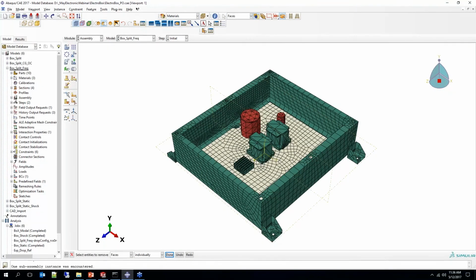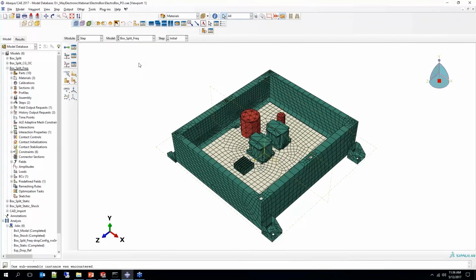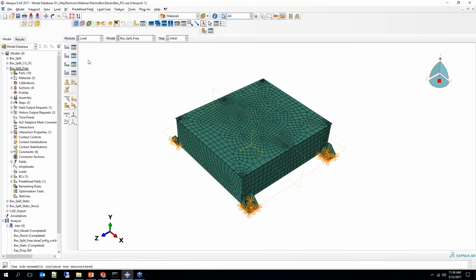We have some choices around that, but basically I used a module where I come in and find contact pairs, and we have some settings here for what type of tolerance, and whether you want to look across the whole model or sub-select some portion of it. But then I've just created a series of ties between some surfaces.